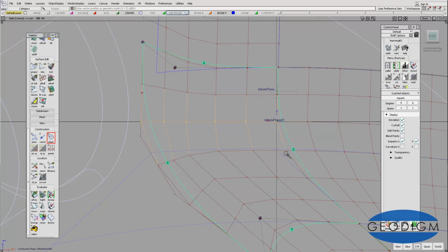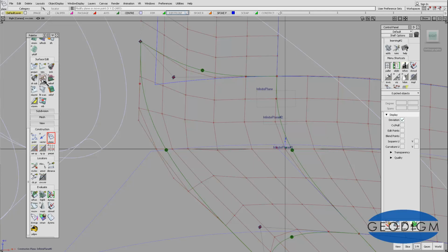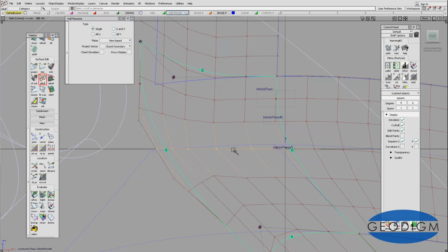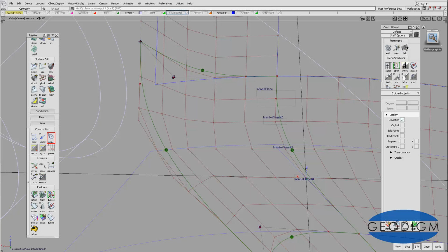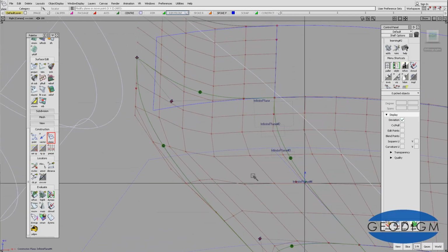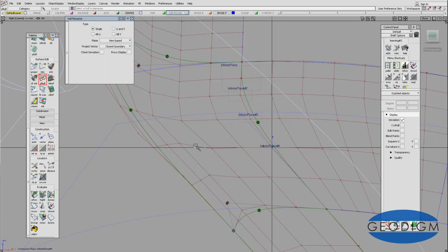So we do the other ones. So it's creating a plane on that CV, and that CV. Press the space bar, right view, planarize. You can see that's almost there anyway. Of course you can do this by eye, but you've really got to then zoom in with a non-proportional zoom window to be able to judge it closely enough.